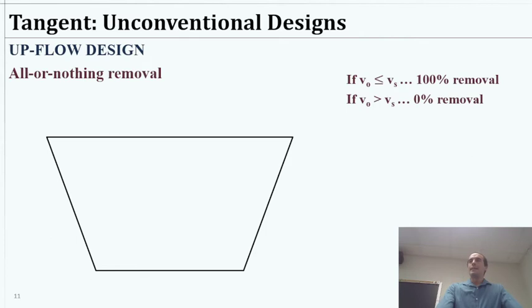One other interesting design is called an upflow reactor, or upflow sedimentation basin, and it's kind of weird because we have a system where we're going to flow water from the bottom upwards. So this is the flow. And as the water is moving upwards, whereas in the circular systems we've dealt with in the past, the water is flowing from the middle outwards, in this case it's flowing literally upwards and being harvested over the edge here.